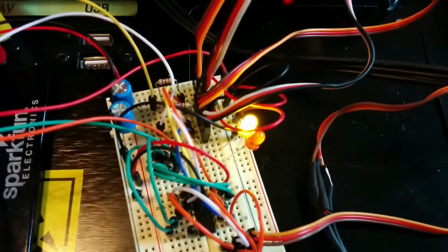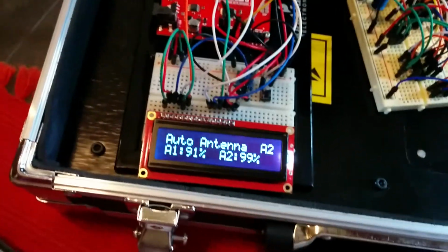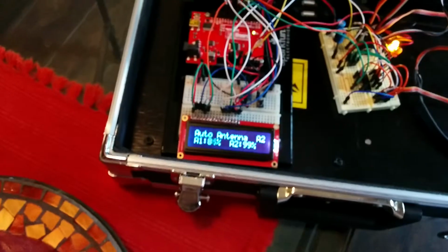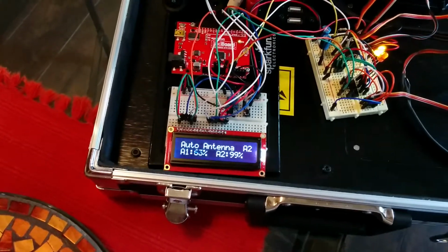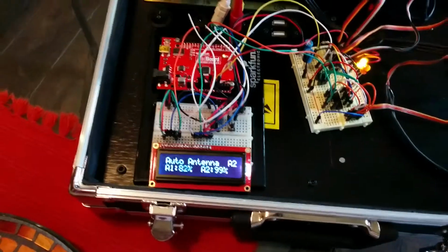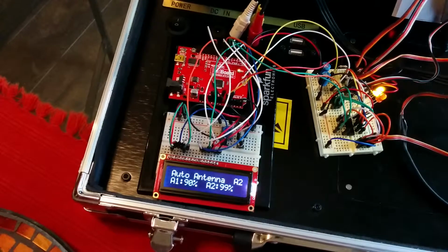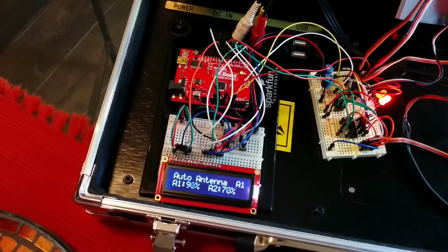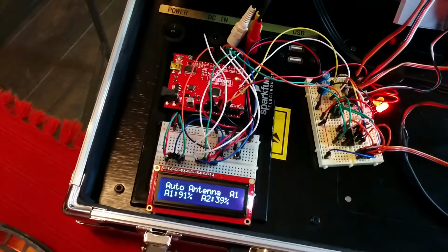And the yellow indicates that antenna 2 is being used, and when red is on, that indicates antenna 1 is being used. And now to watch the RSSI drop, I'm going to cover the omnidirectional with my hand, and you can see the RSSI start dropping. As I let go, it comes back up. Antenna 2 is very hard to do that with, but I'm going to try. There we go. Covering it up, and see the antenna switched. It went from yellow to red.